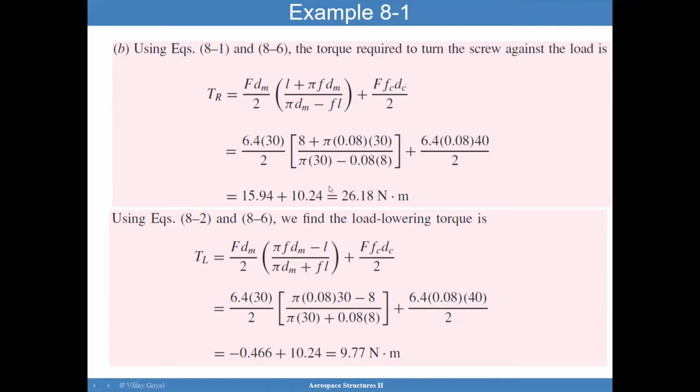And here what we've done is we've added the torque from the collar. So that has been added, which was not shown before, but the torque required is going to have to account for the frictional coefficient between the load and the collar. And so that's what was done here.